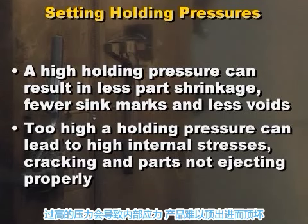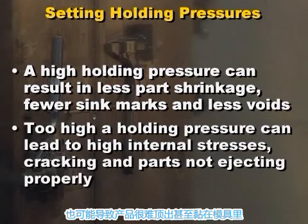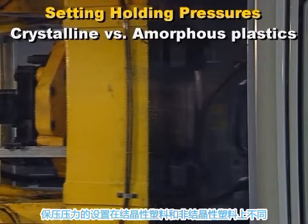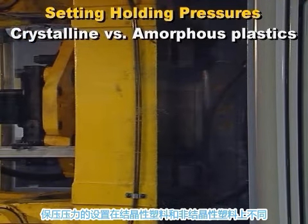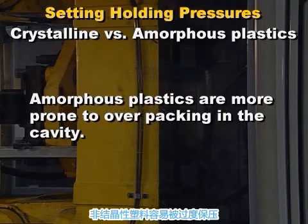Too high a pressure can cause overpacking of the cavities and high internal stresses, which can lead to cracking. It can also result in the parts not ejecting easily or even sticking in the mold. Holding pressure settings can be different for crystalline versus amorphous plastics. Amorphous plastics are more prone to overpacking in the cavity due to their molecular structure.